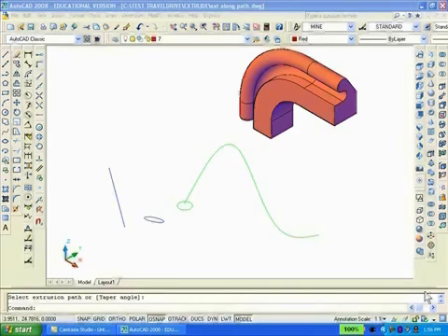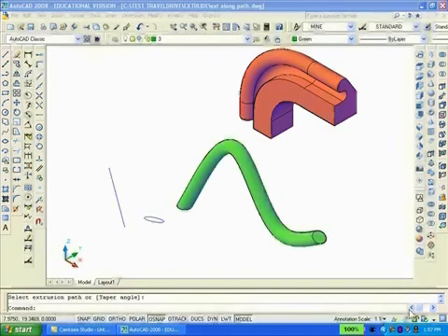I entered the extrude command again, picked the green circle, typed P and picked the green extrusion path. The path used here was a spline curve. Finally, I pressed the space bar to restart the extrude command, picked the blue ellipse and its path, and pressed Enter. You will note that an extrusion path can be at any distance from the profile to be extruded.